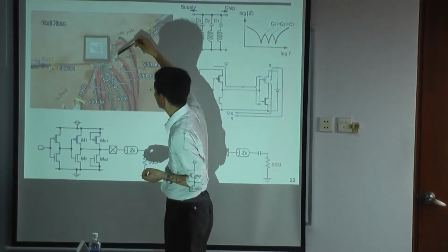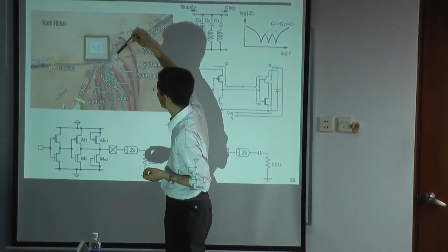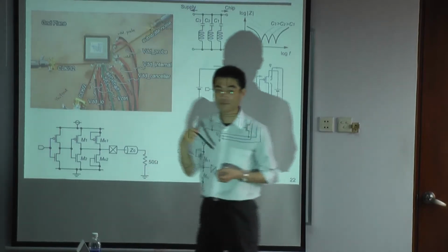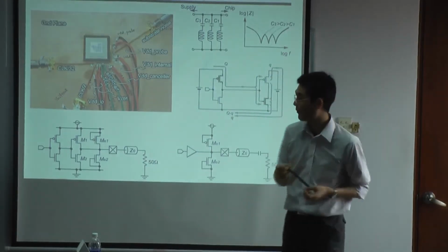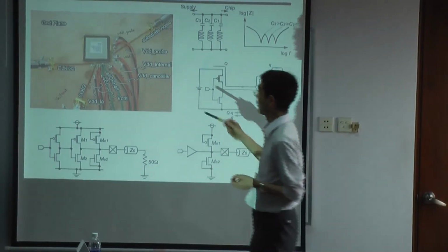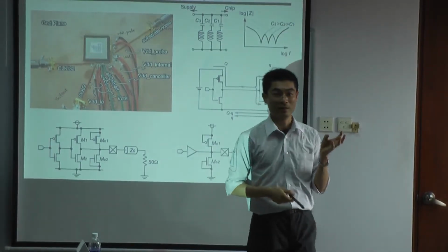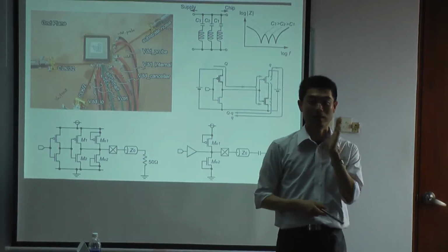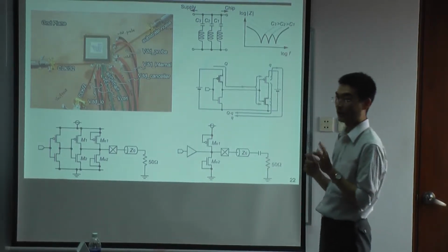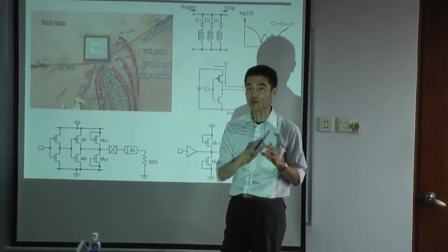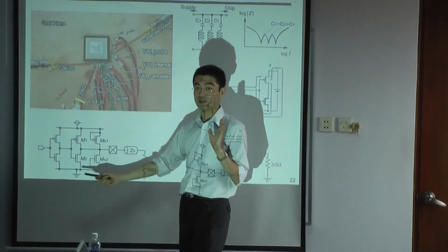For example, here you can see that there are several chip capacitors. And as I told you, I put 1 microfarad, 100 nanofarad, 10 nanofarad, 1 nanofarad, many types of capacitors in parallel, so that we have a small impedance for a wide variety of frequencies.